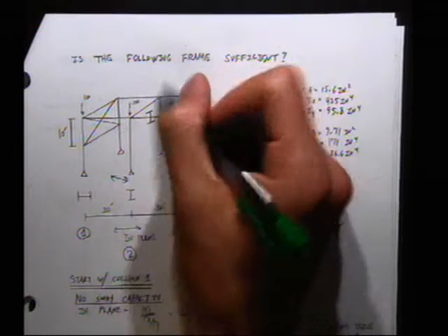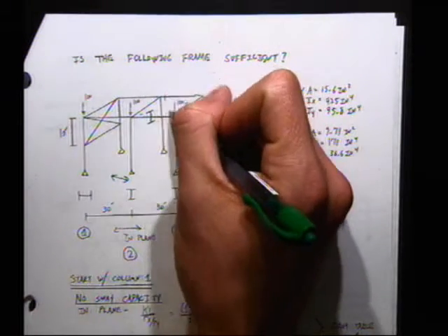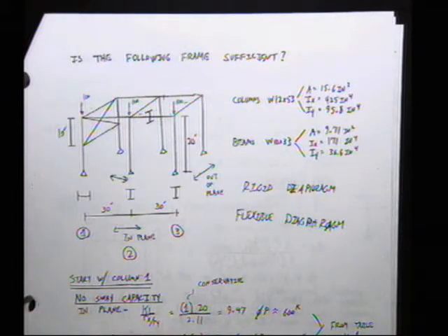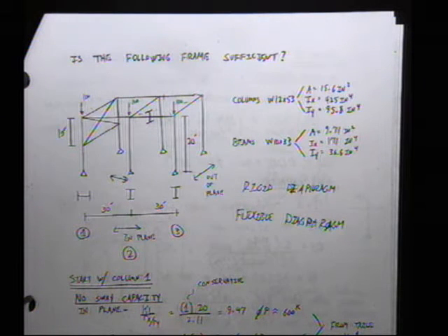Cross bracing in the roof. Have you ever seen that before in industrial buildings? Go up and you look. Talk about something that doesn't cost very much. We run these really thin wires in between, and that's enough to consider a rigid diaphragm. That's enough to consider it. I mean, you get a lot more capacity out of that. Okay, a whole lot more capacity.